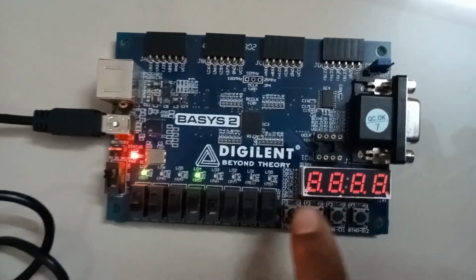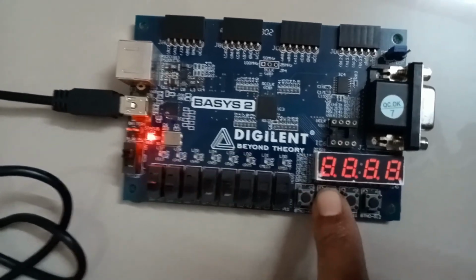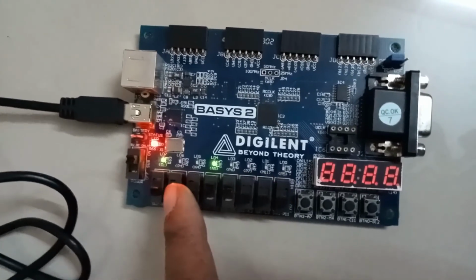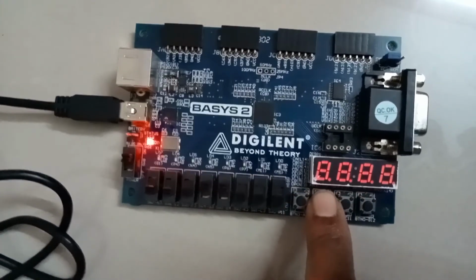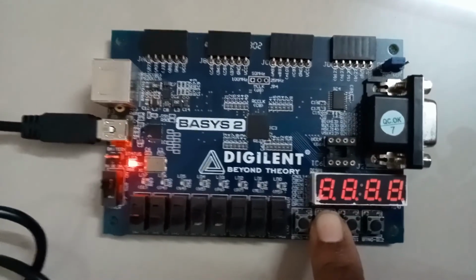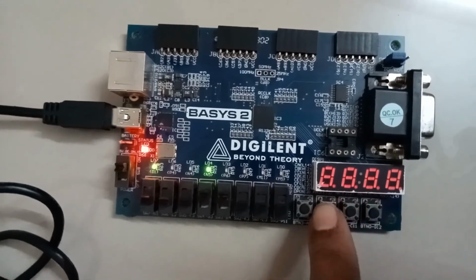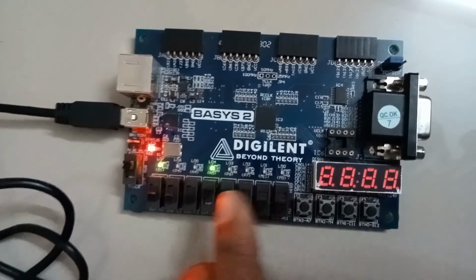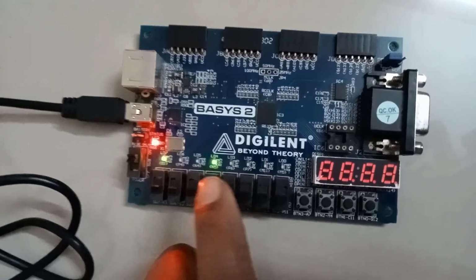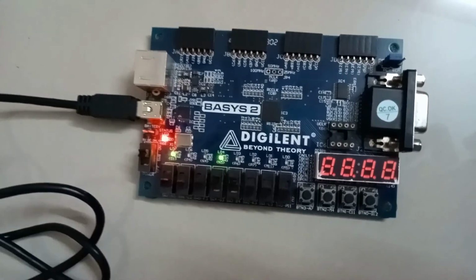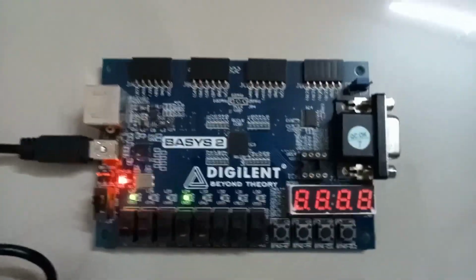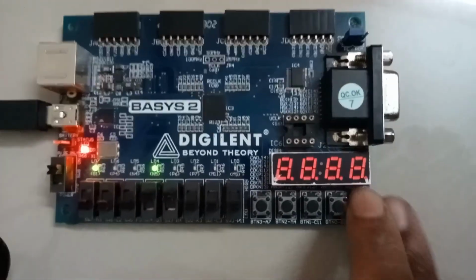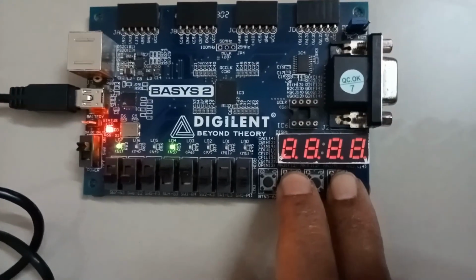The next one is 4, so this is 1, 0, 0. Press 1. It is nothing but the AND operation. A is 8 and B is 1. 8 AND with 1, the output will be 0. So press this button and check that the output is 0. Next one is 1, 0, 1. Press this, and it will perform the OR operation. A is 8 and B is 1, so 8 OR with 1 will be 9. You can press the same button again and observe the result. So this will be 101.